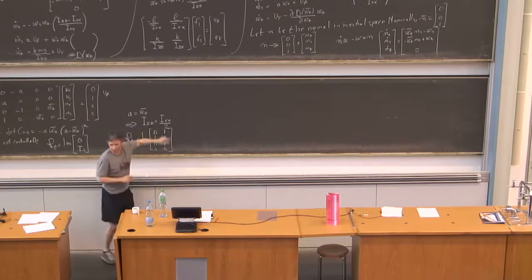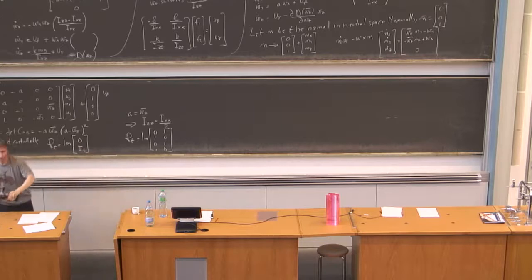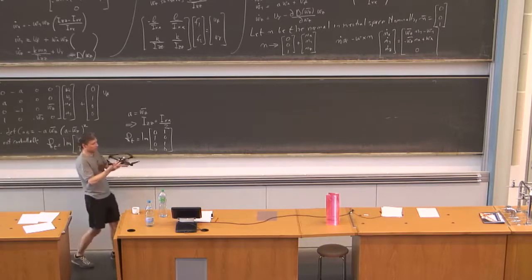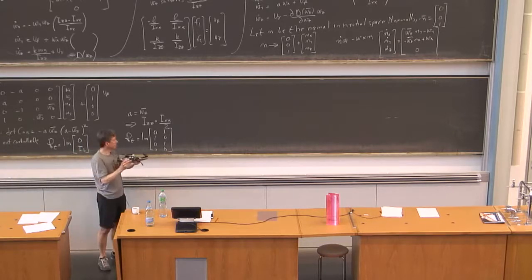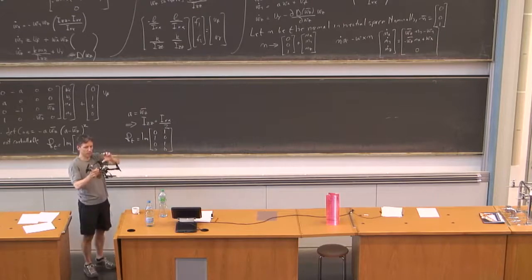And what this is basically telling you is that you can't fly this thing if the mass moment of inertia about z is double that around x. And interestingly enough, for any planar body, this relationship holds. So this tells you that if you were to make a really flat quadcopter, so here it's not perfectly flat, but it's relatively flat, it makes it difficult to control.